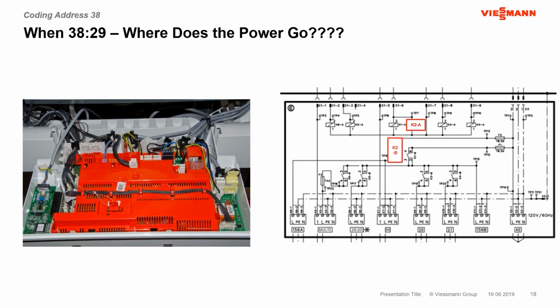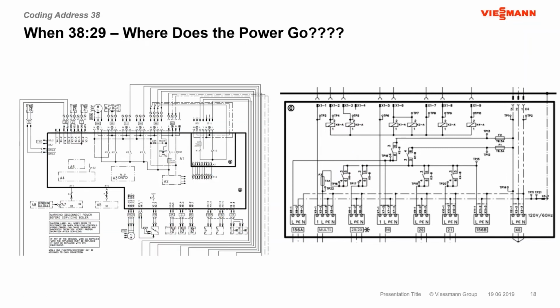K2A energizes, when you energize K2A, it closes the contact at K2B. And K3 closes K3B. K4, I think we're all getting the picture here of how this works, but they just separate in the document. This and this are one component. That's the relay. We're just separating the coil from the switching relay down here at the bottom. All right, so we move through that, open up, and I look at the control schematic.